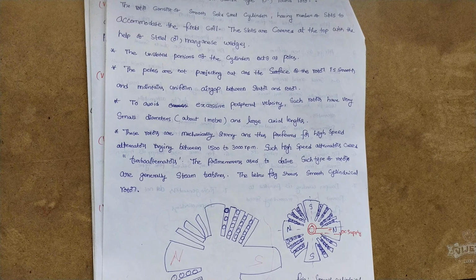It is very important. Full pitch windings have harmonics, hence short pitch windings reduce the harmonics, and the waveform of the induced EMF is more sinusoidal. Short pitch eliminates high frequency harmonics, hence the EMF waveform induced in the armature is more sinusoidal. Another advantage is that when high frequency harmonics get eliminated, eddy current and hysteresis losses, which depend on frequency, get minimized.